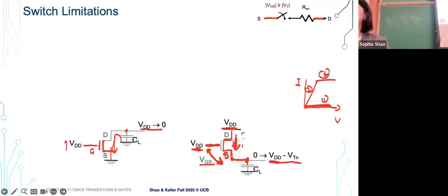We're talking about the gate voltage. The gate to source voltage needs to be greater than the threshold voltage to even have a conducting channel, and that is the first region we talked about. So the behavior is related to the first region: if the gate to source voltage is less than the threshold voltage, things are not conducting.